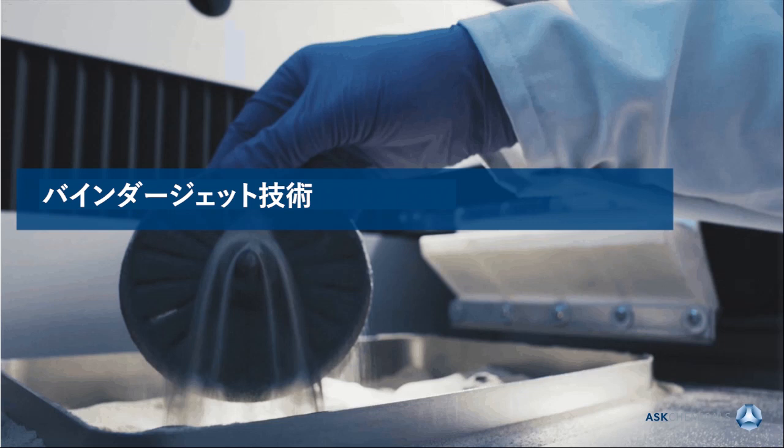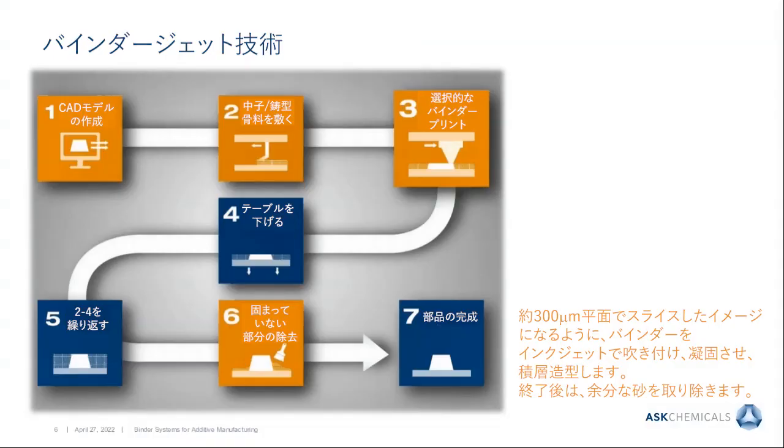Let's take a look at binder technology itself. Many of you may already know the process of binder jetting or additive manufacturing, coming from a 3D model on the computer, which is then sliced into two-dimensional images. A thin layer of molding material, typically a thickness of around 300 microns, is spread out on a building platform and afterwards selectively printed with binder according to the 2D data generated.